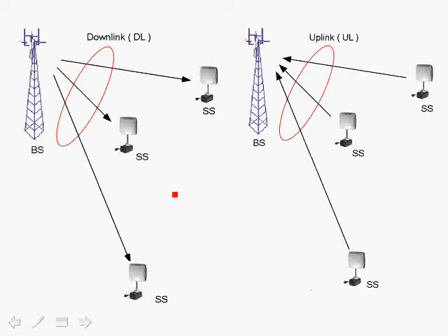Going to go in depth of how subchannels and slots are allocated and how the base station actually sends information to the subscriber stations so they know exactly which set of data regions are associated with their data, and what data regions they have to use in order to send information back to the base station. So a very important topic's coming up. Actually, there's only about 3 pictures that we're going to show that tell the whole story.